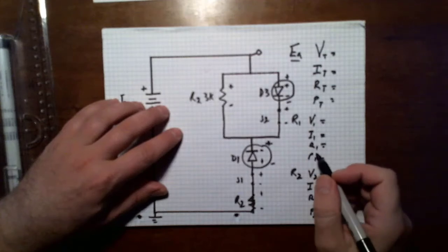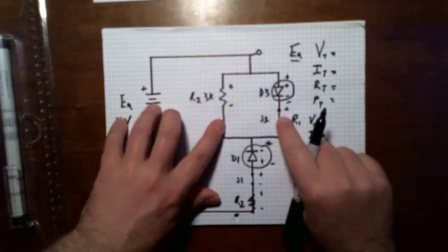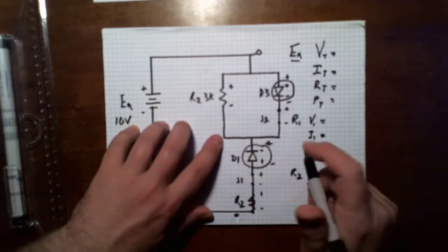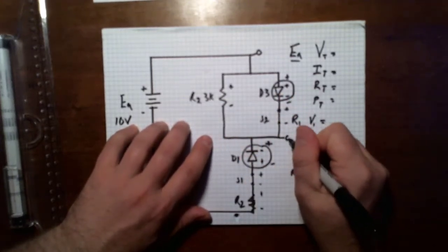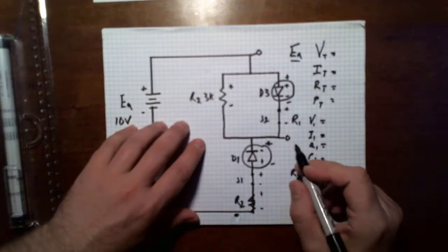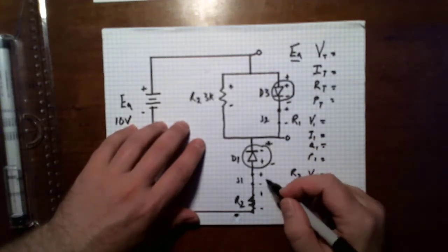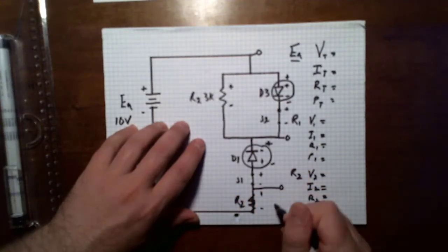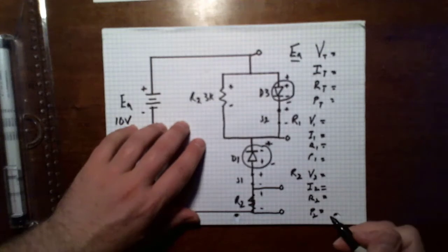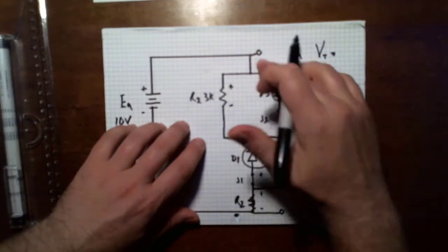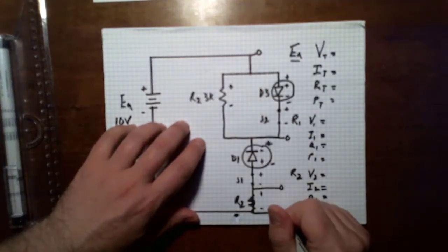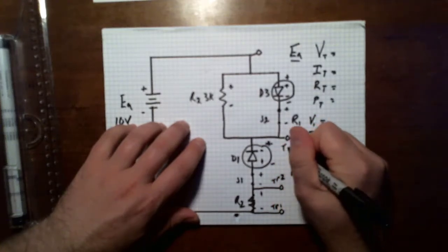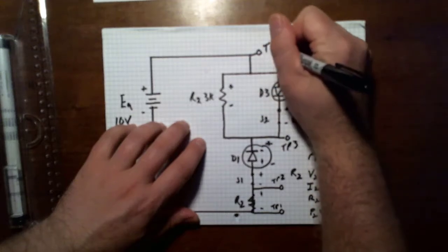So I'm not going to put a test point there. I have continuous run here between this resistor, this diode, and this diode here, so I'm going to toss another test point here. I'm not going to worry about the switch down here, but I do have a resistor and a diode, so I'm going to throw a test point in here, and one more at ground. So I have 4 test points. I'll label them TP1, TP2, TP3, and TP4.